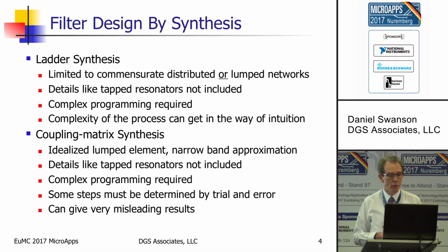Then coupling matrix synthesis is also very popular, but the coupling matrix is really an idealized lumped element network when you translate it into the bandpass domain. It's a narrow band approximation. Again, details like tapped resonators are not there. You're going to have to put those in later.